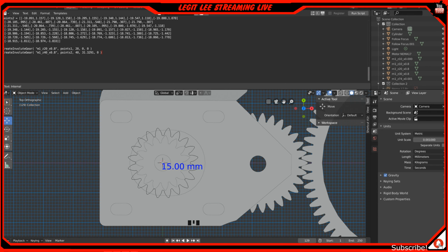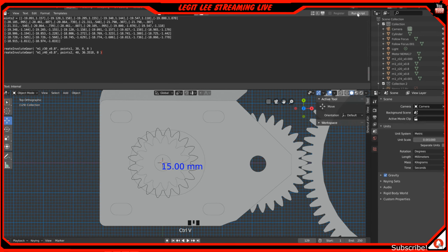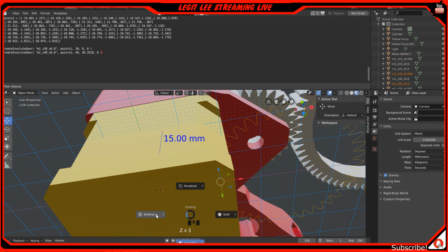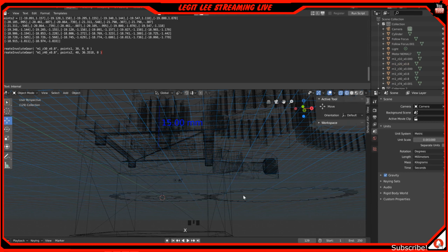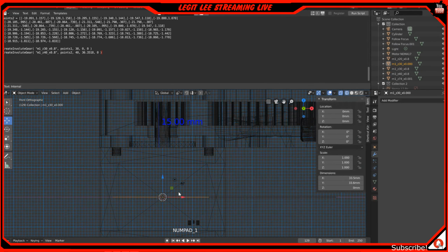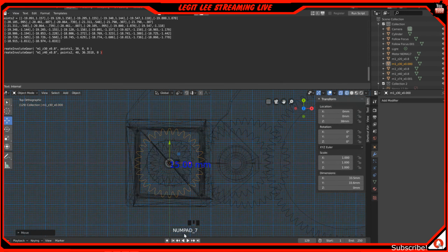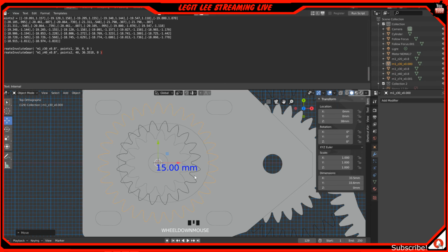If we calculate, copy this, copy, hit, paste, run, wireframe. Whoa, wireframe. You don't want this guy. That's deleted. Delete it. Alright. Sorry guys, a little cough there. Drag it up to the top. There we go. And we are going to do solid mode. And yeah, that doesn't hit anything. That's good. It gets close to those bolts, but not close enough. So that's actually kind of good.